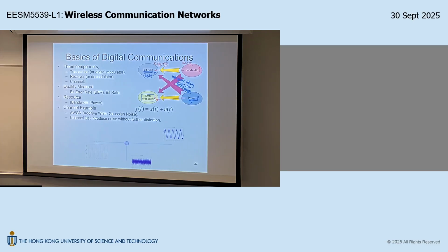Okay, so this explains this modulation family, either MPSK or MQAM. This is the modulation family you would use if you want to engage in this trade-off direction. When you use this, you have to sacrifice the power. You want to save bandwidth, okay? You cannot increase bandwidth, so you sacrifice the power. You don't mind increasing the power. Power refers to signal-to-noise ratio, okay? You don't mind increasing the power so that you can increase the bit rate without increasing the error probability. So that's the situation when you want to use this modulation family, okay?